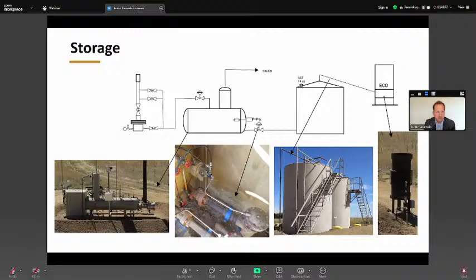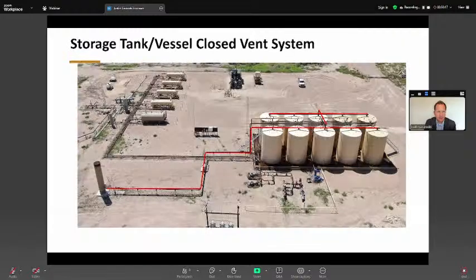You've got your wellhead coming into some type of separation, multiple stages of separation, with dump valves that are being controlled by level. And those are going to your tanks, they're going to multiple stages. From your tanks, then it's going to your control device, your enclosed combustor, a VRU, or a flare. And then we want to break down how we're actually evaluating our tank system. So you've got our vent for the tanks highlighted in red.